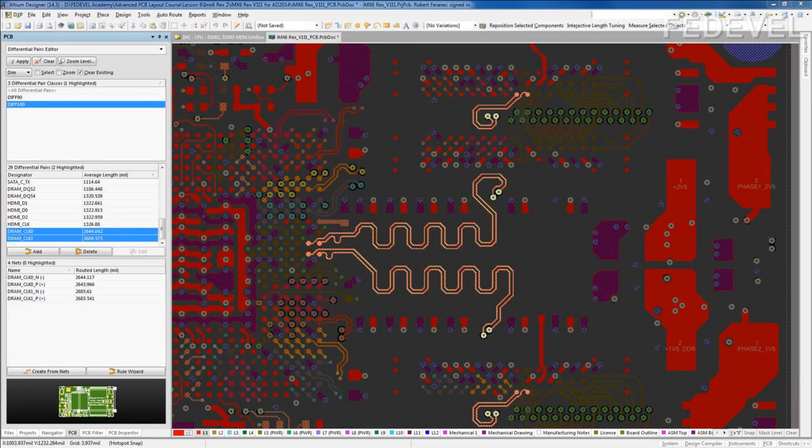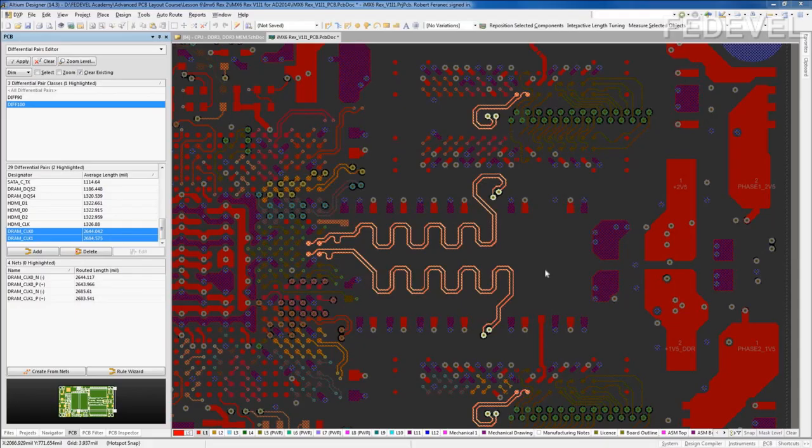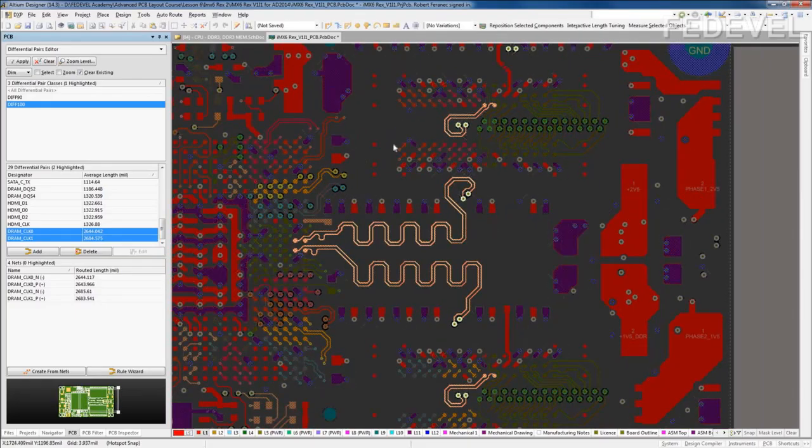And one more tip from memory length matching. Always be sure you leave enough space for the clocks, because the clocks are usually the longest signals from the memory interface, and you will need a lot of waves to length match the clocks. Very often I do the waves of the clock on top or bottom layer, because usually I do not draw any other signals on these layers, so there is a lot of space, as you can see here, for example.